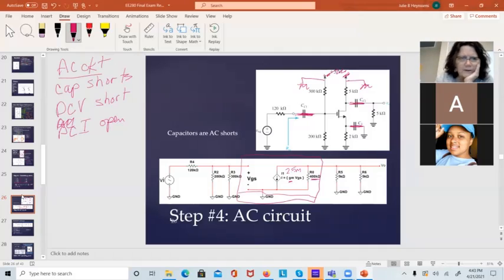Now I've got to take this model that I've got down here and fill in where things on the circuit are connected. Did I miss the source resistor? Yeah, I did. Oh, no, I didn't. Because on the source, you've got a short in parallel with a 2 k ohm resistor. That is going to be a short to ground. So my source here gets grounded. That is correct.